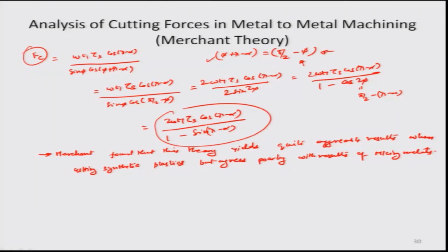So, there was a small modification done by P.W. Bridgman, who realized that the shear stress, ultimate shear stress tau s, is not completely independent of the normal stress sigma which would come into picture. In fact, the alternate theory he proposed was that can we relate the tau s to a basic tau s0 value plus something proportional to the normal stress sigma that is coming at the shear plane, okay, where K1 is a constant and sigma is the normal stress acting on the shear plane.